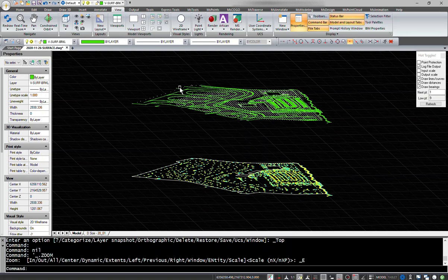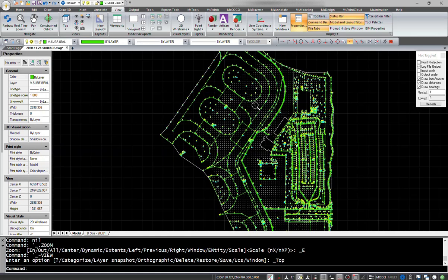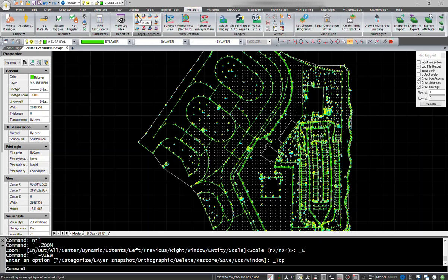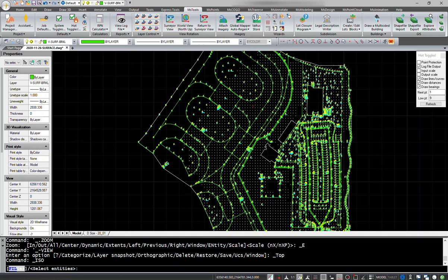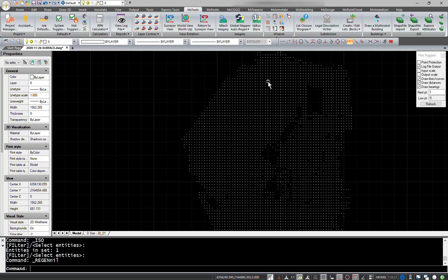and in the end we want to create some contours. So first thing that I'd like to do, I'll get back to my top-down view here, is just use the points that were generated using the points on grid routine in the point cloud ribbon to start making a surface. So best practice is to use the isolate layer tool, and I'll just pick on one of those point nodes and it will freeze all of the layers except for the points layer.